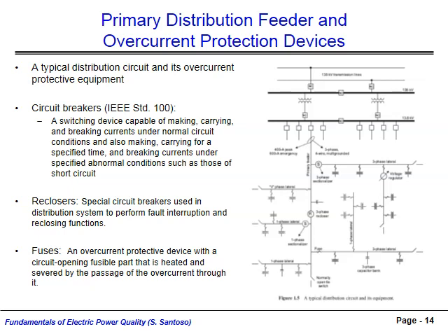Therefore, reclosers are often coordinated with the fuses to clear temporary faults, with downstream customers experiencing momentary interruptions, giving the fault time to clear and saving the fuse from blowing. While recloser operation often causes momentary interruptions for a larger number of customers, they may help prevent sustained interruptions caused by blown fuses.